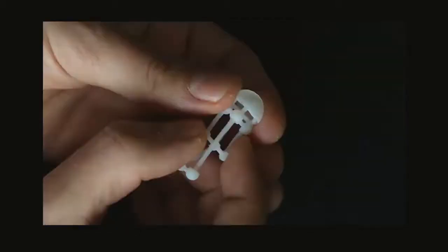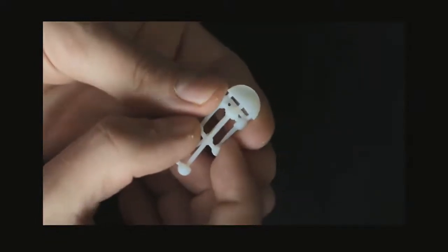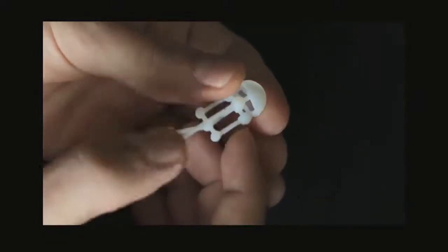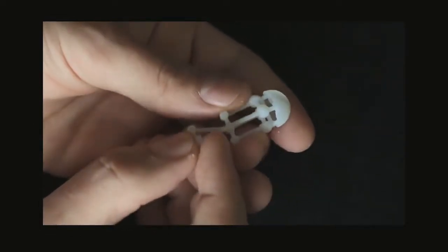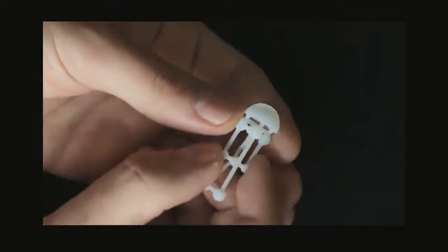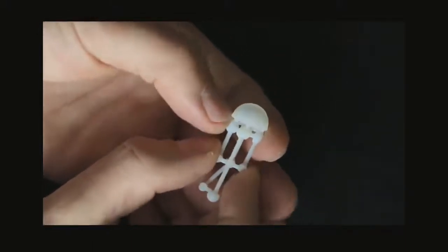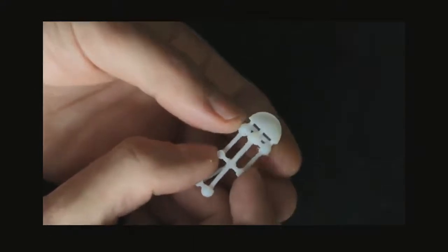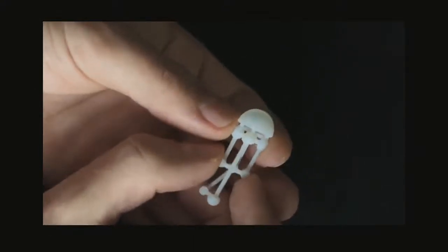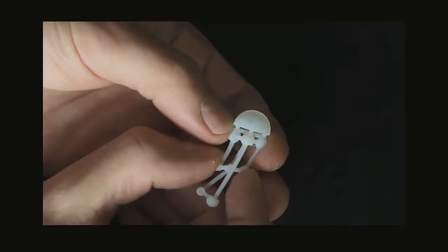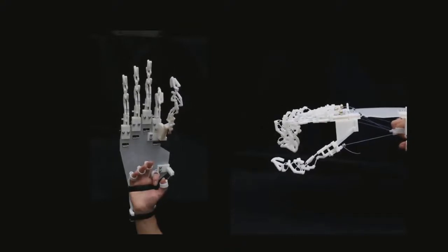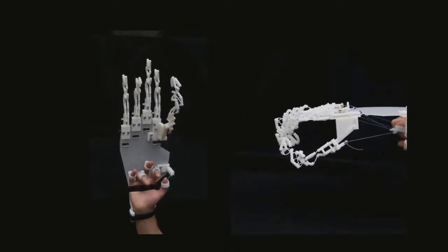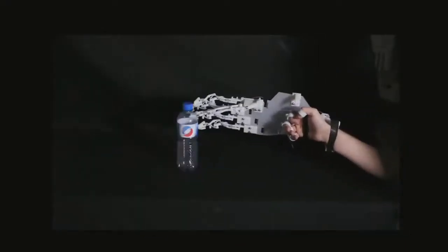And when we tried to make this eye mechanism using a conventional approach, with rigid joints, the residual support material in the spherical joints, we couldn't get it out, and it made things so stiff that before the mechanism was able to move, the members, the individual links, deformed significantly and actually broke before we could actually move and use the mechanism. Here's another example that indicates a little bit how this system could also be used for compliant robotics or custom prosthetics.